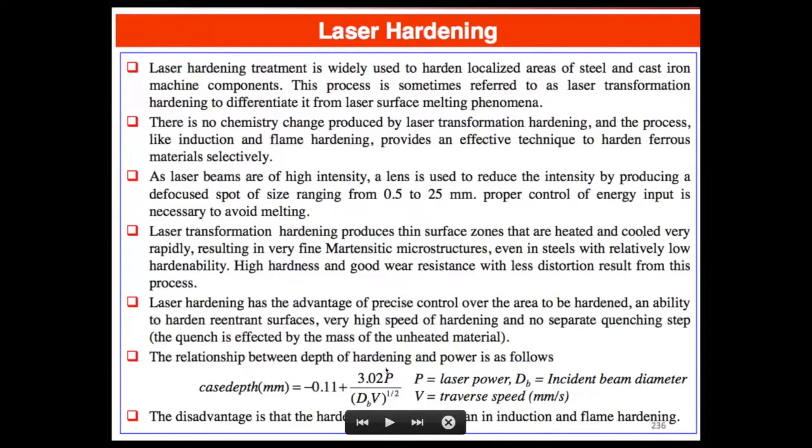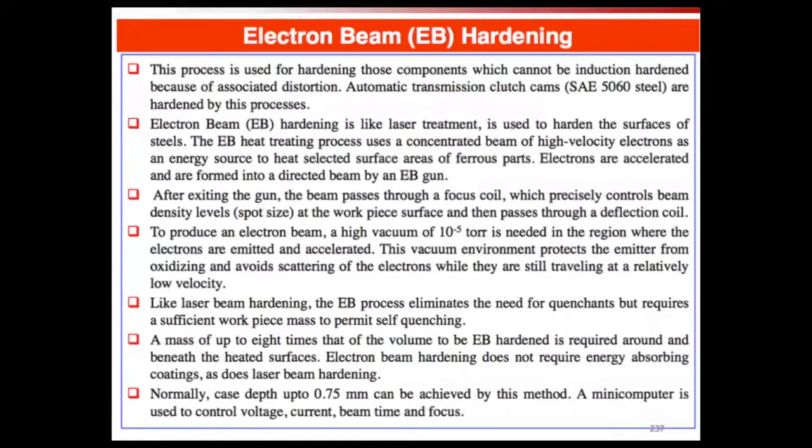Since the depth of heating from the laser is very small compared to that for induction or flame hardening, you have a much thinner case hardened layer on the outside. But again, you have that compressive stresses that you get from a peening operation as well.